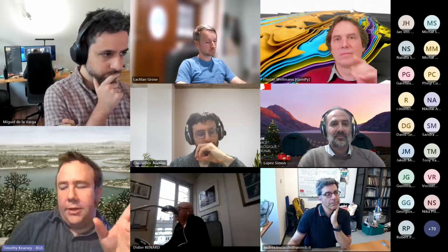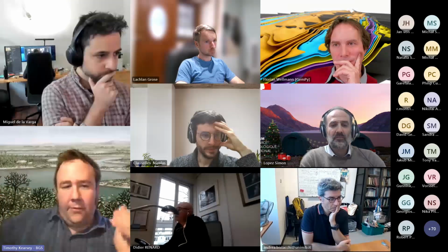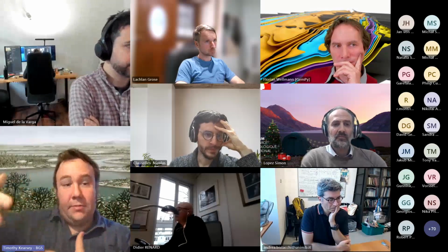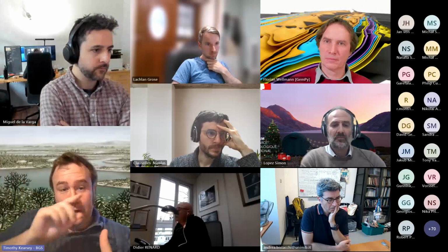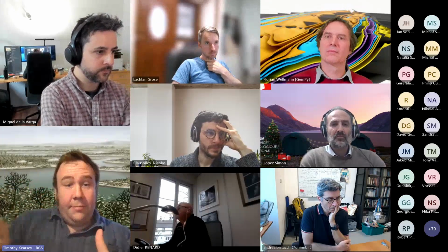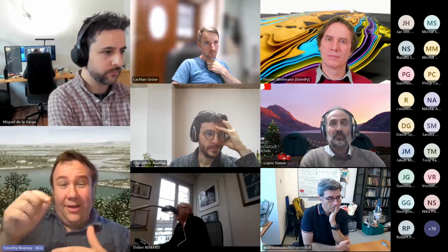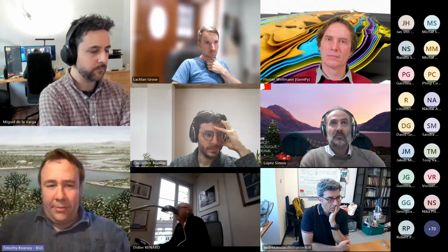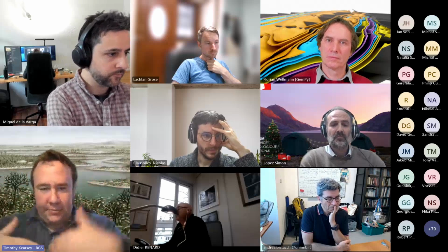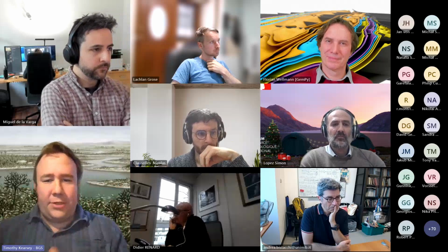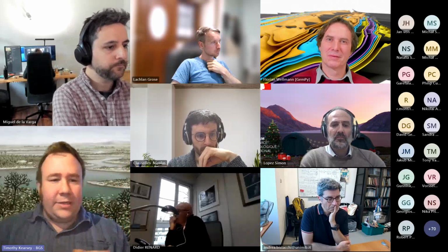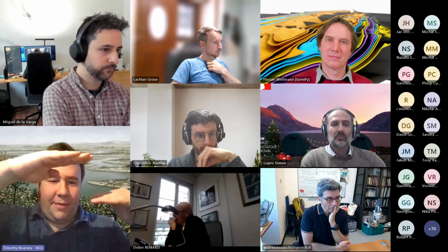Just following on from that, one of the things I'm increasingly doing, and this is using GeoGoCAD, is starting off with the faults you can see in seismic, because we know they're there, and they often are the big structures that are defining your domains within your model. And then not fitting the model to the markers, and using that residual on your borehole data and your import data to highlight areas where you need a fault. Quite often I'm doing near surface modeling, mostly in coalfield areas, and we have thousands of faults on our maps, many of which are some miner saw something that displaced something by half a meter.